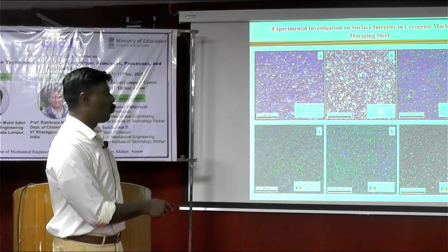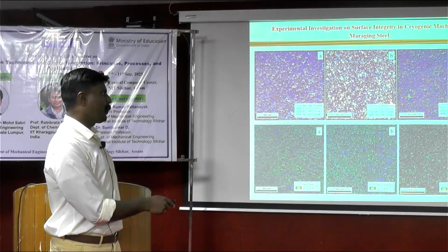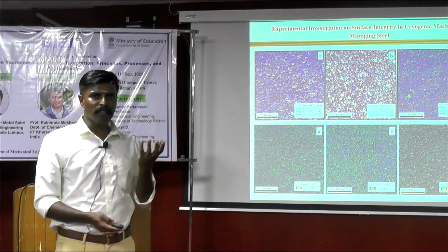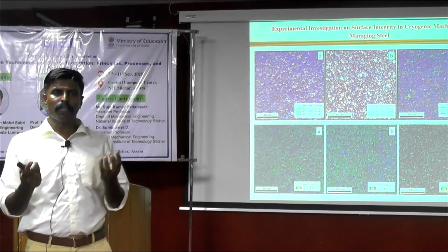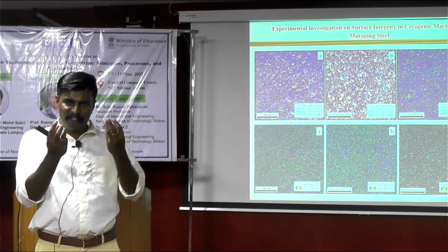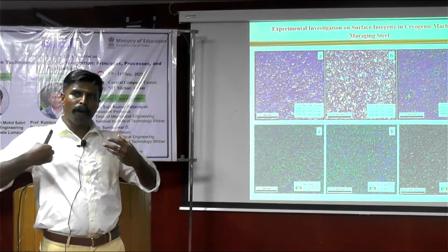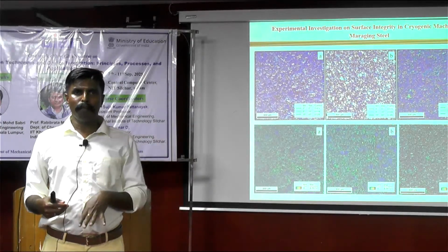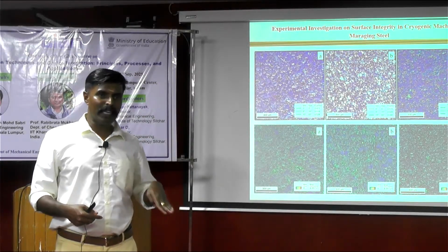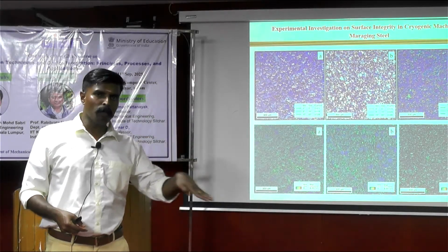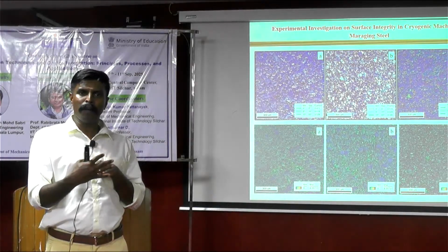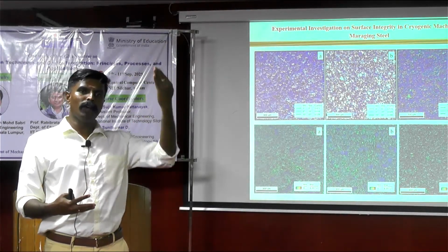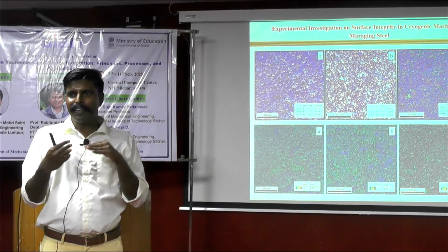Here you can see 1 degree to 5 degree, 5 degree to 15 degree, then 15 to 65 degree. Actually, the grain boundary means the two solidification fronts meet; that region is called grain boundary. Grain boundaries are strengtheners for the material. For example, at room temperature, if any deformation happens, the slip system will move. If there is any grain boundary which will hinder the slip movement, obviously the mechanical property will improve. So the grain boundaries are hindering actions here.